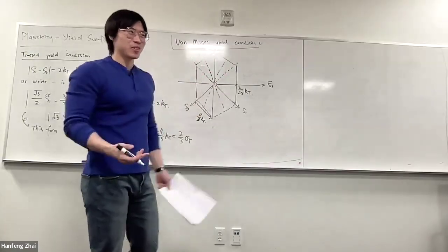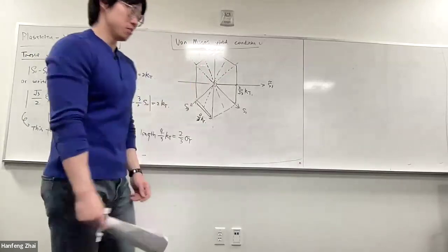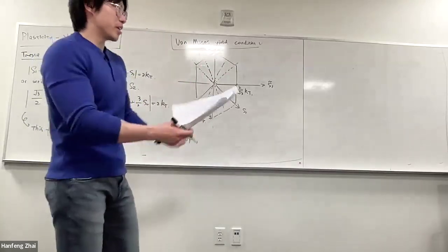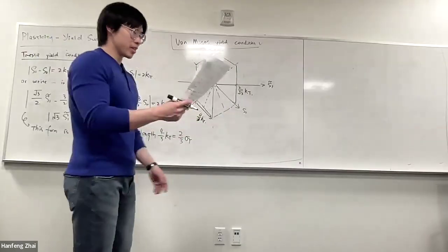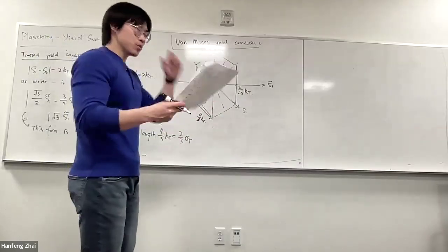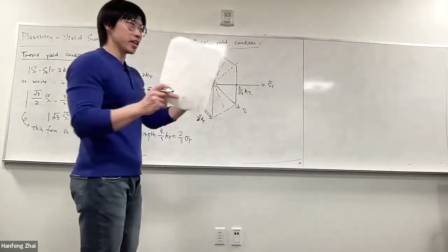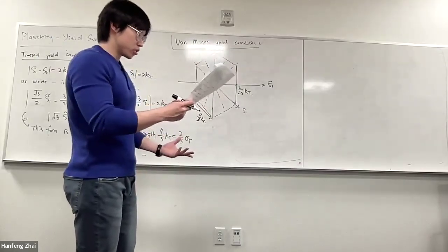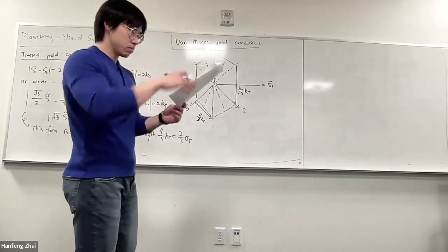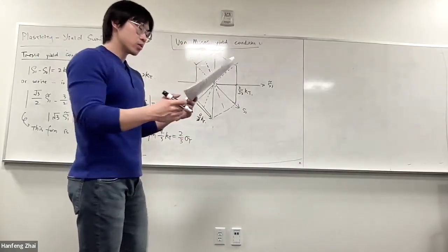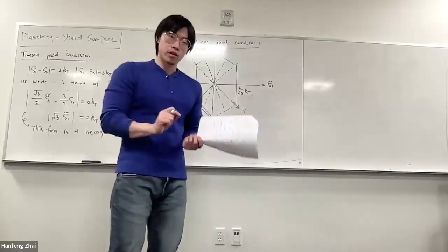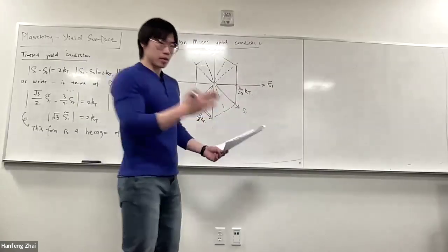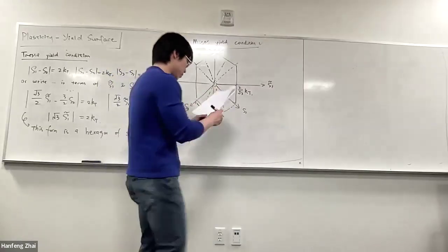If this is a lecture, you would naturally expect me to ask a question: what's the connection between the Tresca and von Mises? I will not literally ask you to do the algebra because it will be too complicated. But if I were to ask you to make an educated guess, what will be your intuition? The conclusion is the Tresca yield surface, or the yield condition, is inscribed by the circle of the von Mises yield criteria. So I'm going to write it down, and then I'm going to sketch it to explain what I mean by that, right?